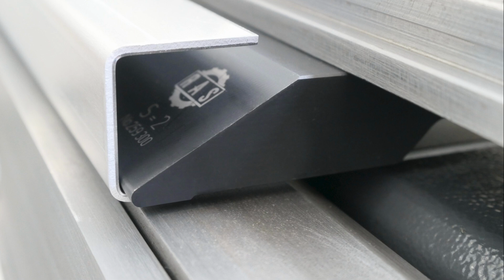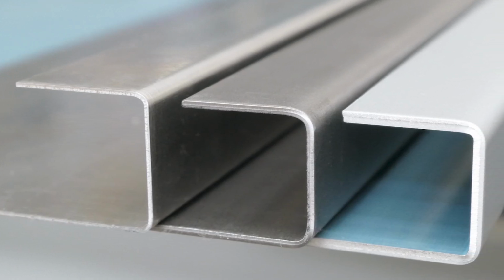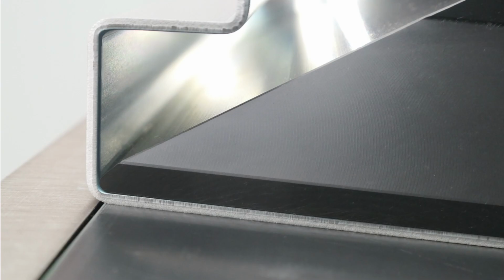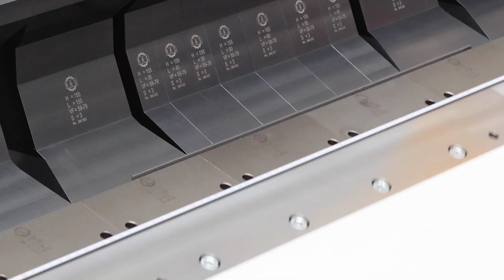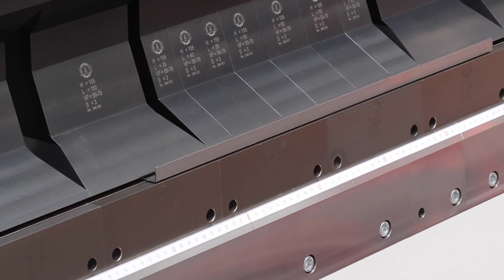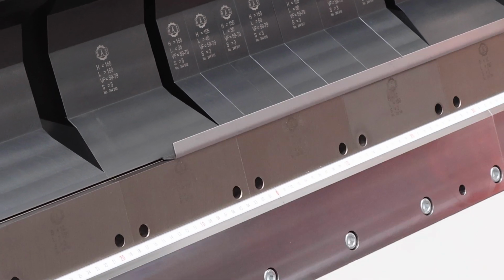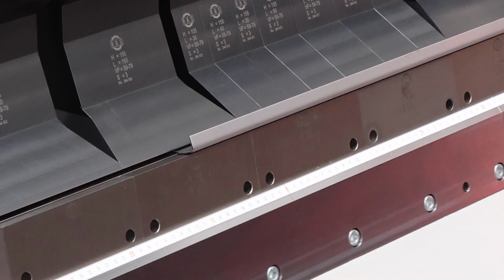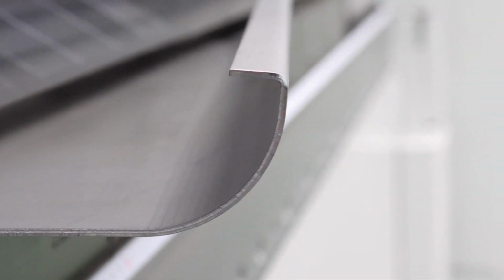Sometimes you need a tool with a small radius due to the material properties. For example, sheet metal producers will suggest a minimum bending radius for aluminum used in roofing and facade industries. However, more often a procedure called step bending is utilized. This allows sharp edge bends and radii to be combined into a single process. The radii are created by stringing together short bending segments. Special tools are not necessary for this method.